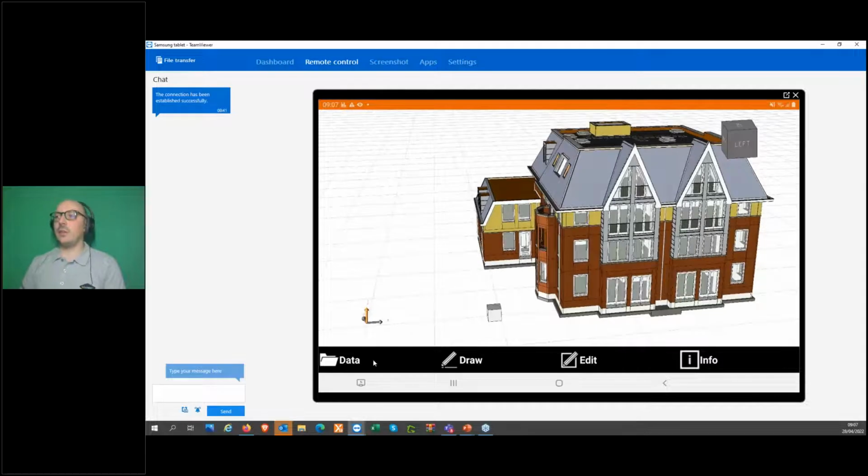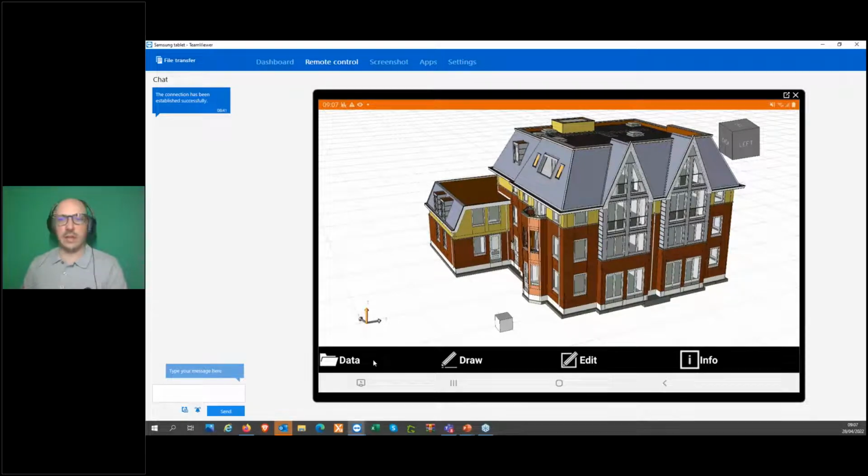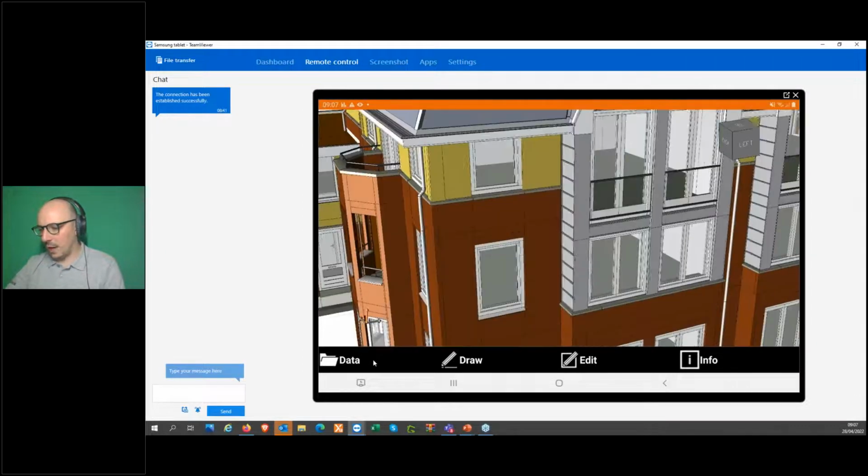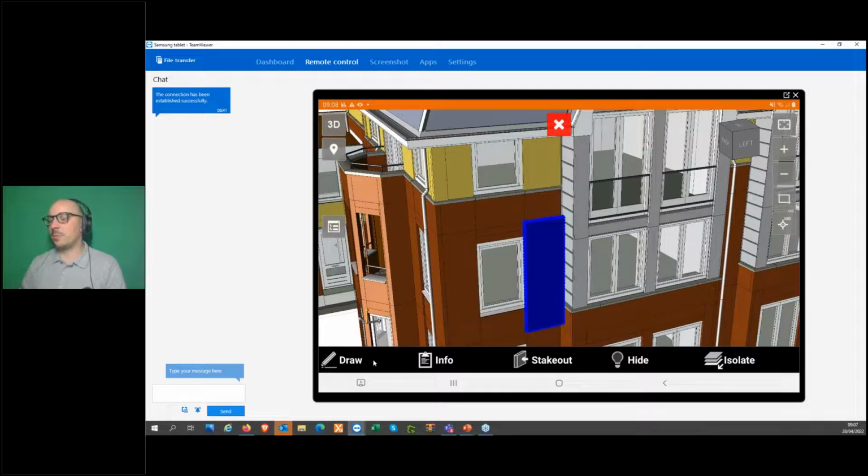So you see here we have the 3D model. What we can do? We can work with a GPS. Most probably we will work with a total station. The difference is that we will work in 3D instead of 2D. So we can create the point on the IFC model. We can do, for example, a free station, selecting the points here, orientate our total station. And for example, I don't know, we can select a surface and stake out, as you can see. So in this case, we will not stake out a point, but we will stake out a 3D surface.